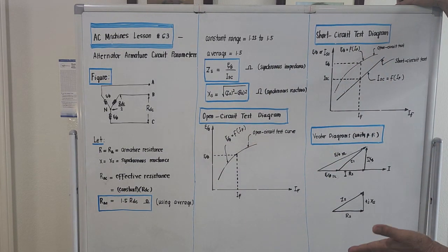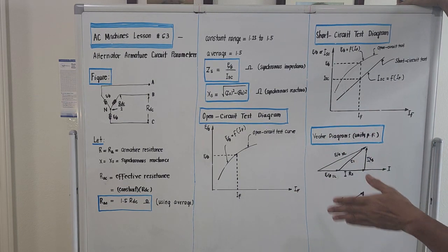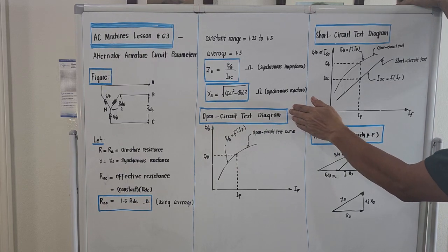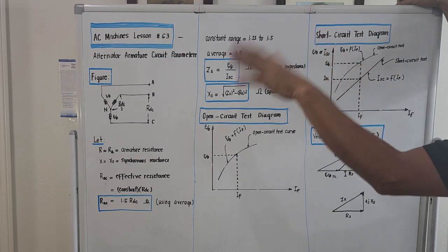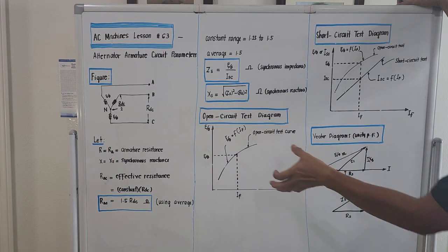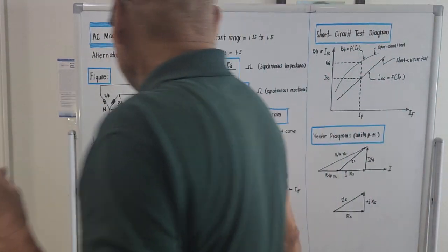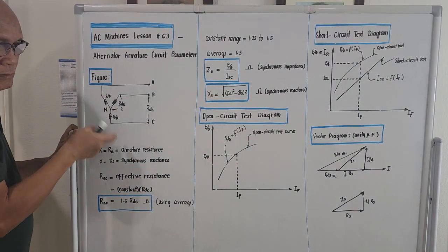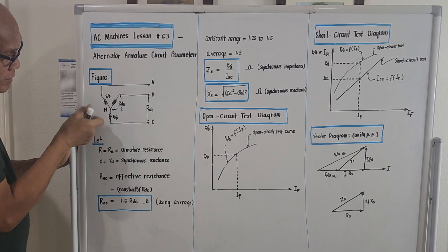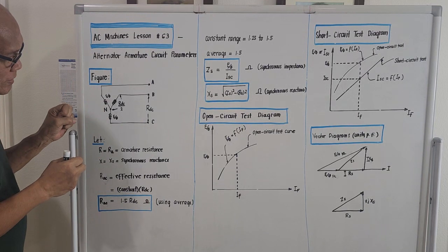And actually, the way we engineers do it is by performing the open circuit voltage test and the short circuit test. Oh, this is now just a summary. If you try to read our book, it's a complicated thing, but this will now be the summary. Okay, let's proceed. Considering for the meantime that the alternator is connected in Y connection. This is one phase, it's three phase, right?